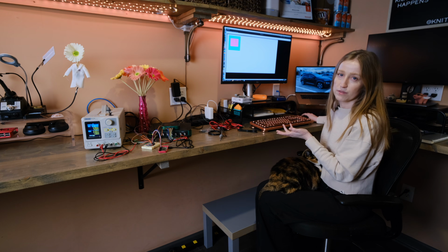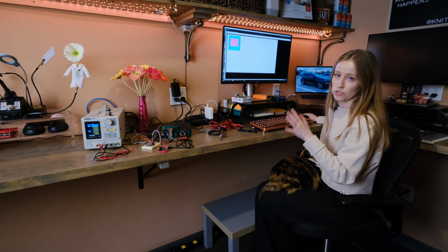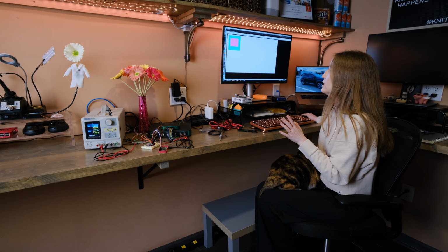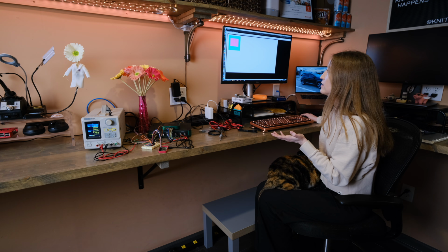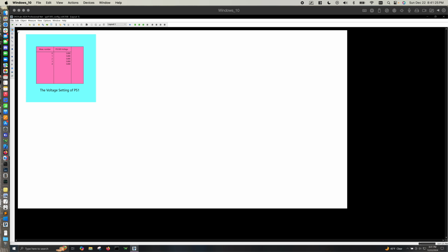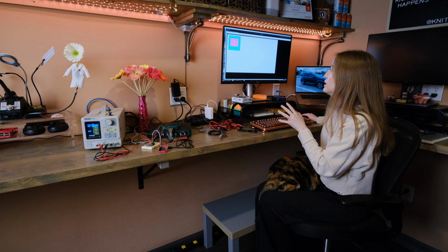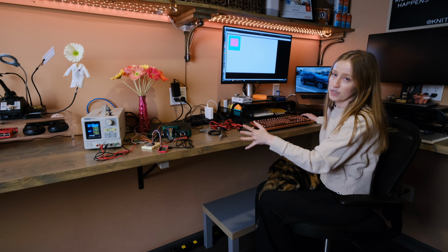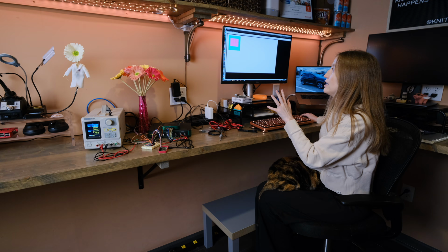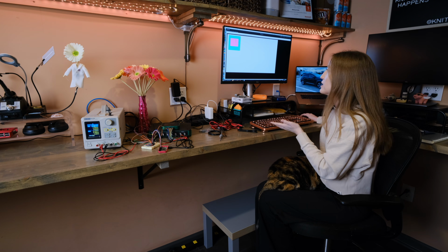So there you go. That's how you create a GUI. Very fast, took 2 minutes. So I can save this, I can run it again. Hitting the run button from the layout view is the same as hitting the run button from the worksheet view. It's going to run this particular worksheet. And see, it hits the stop criteria, and it's automatically stopped on its own. So that's how to create a simple worksheet, create a GUI, and create some sort of stopping mechanism.